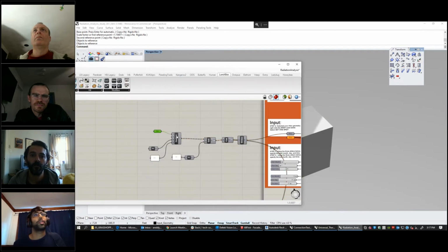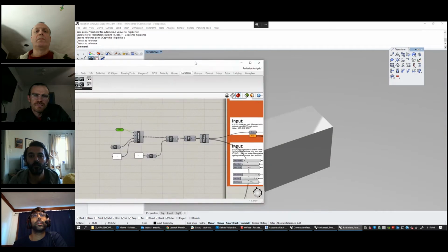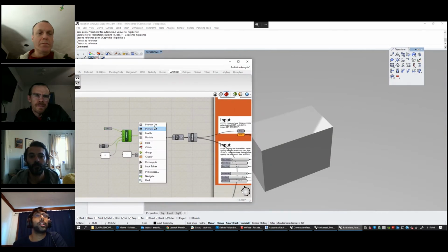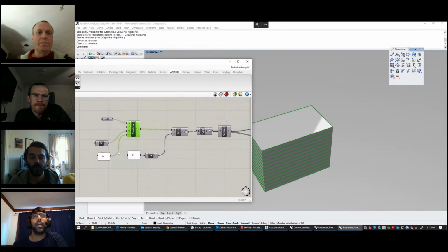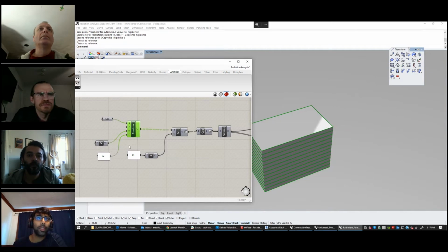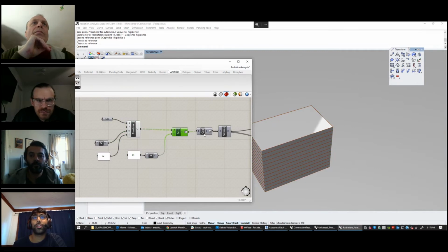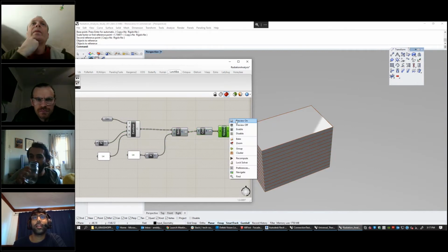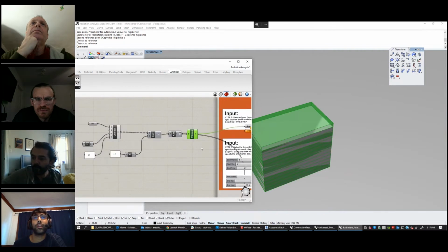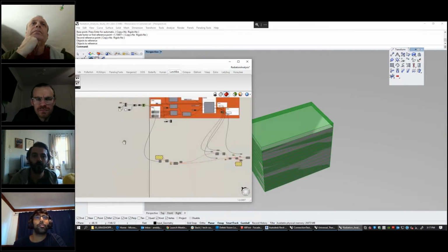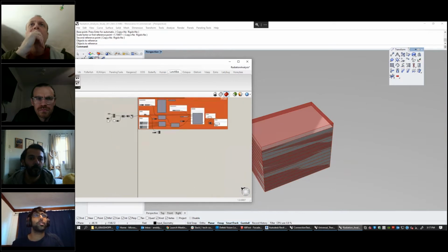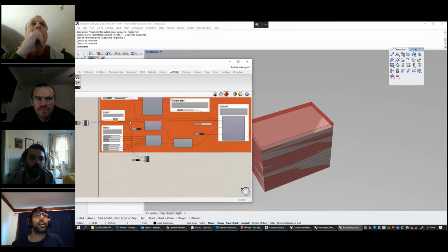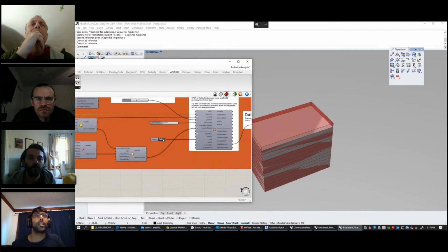Okay, so I'm going to set this one geometry, but I'm also going to contour it. I'm going to get the floor levels and build a nice little floor-by-floor model of this building. You'll see later on why I'm doing that, but basically I'm contouring at every 14 feet, making 14-foot extrusions, capping them, and then using solid union to put these all together. I'll start from scratch here, and then you can see what I'm going to do with all of this. So if we just run the analysis, we put this object into